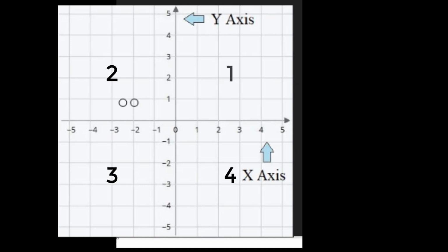Alright, when you look at this Cartesian coordinate system, the increment of each block can change depending on what you're programming. So most CNC machines, an inch will take a 4-place decimal. We're going to be programming everything right now to a 3-place decimal, so in the 1,000th scale. But looking at these blocks on this Cartesian coordinate system here, every block on this system is 1 inch. So we would be programming in 1-inch increments. We're going to be writing a sample program here in a minute.